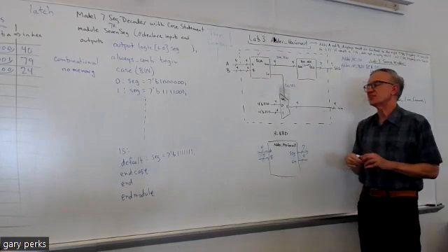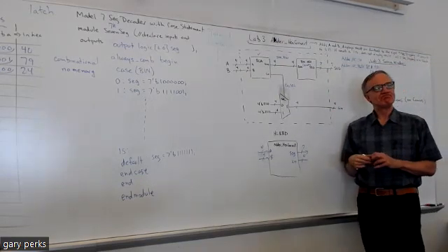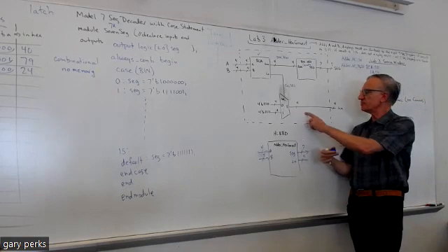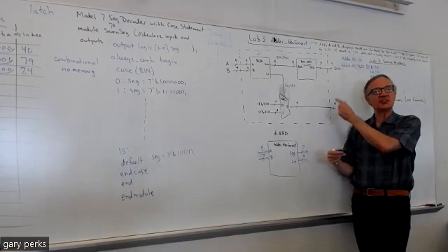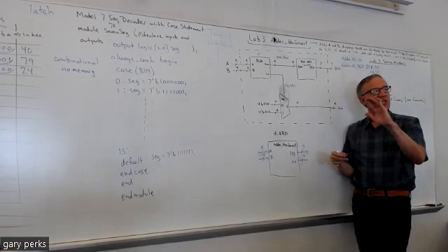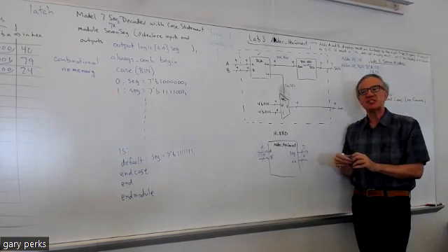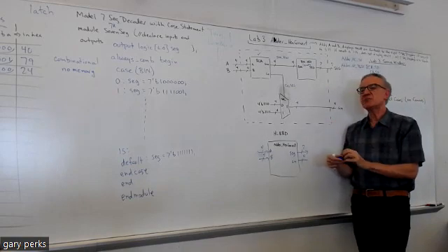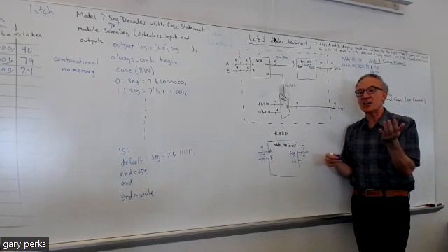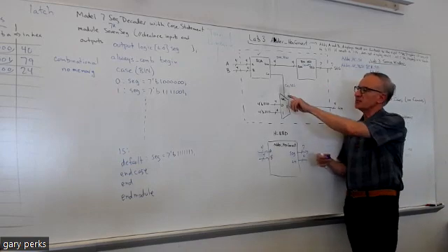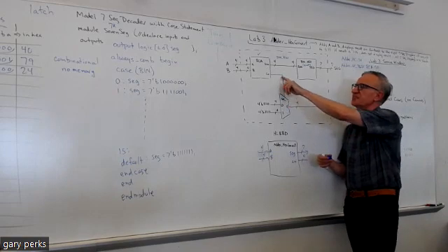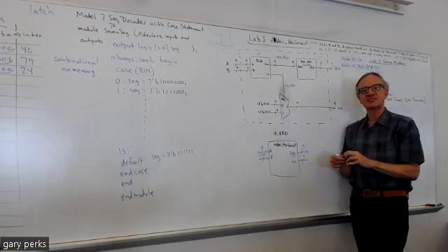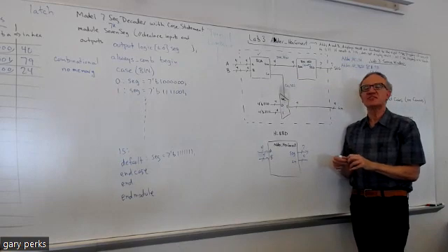Okay, but what is this mux doing? Notice that the output of the mux goes to the AN bits that we just talked about. There's an AN bit that goes to each 7-segment display, and the AN bit determines whether the display will light at all. And then look where the select goes. The select goes to the carry out.